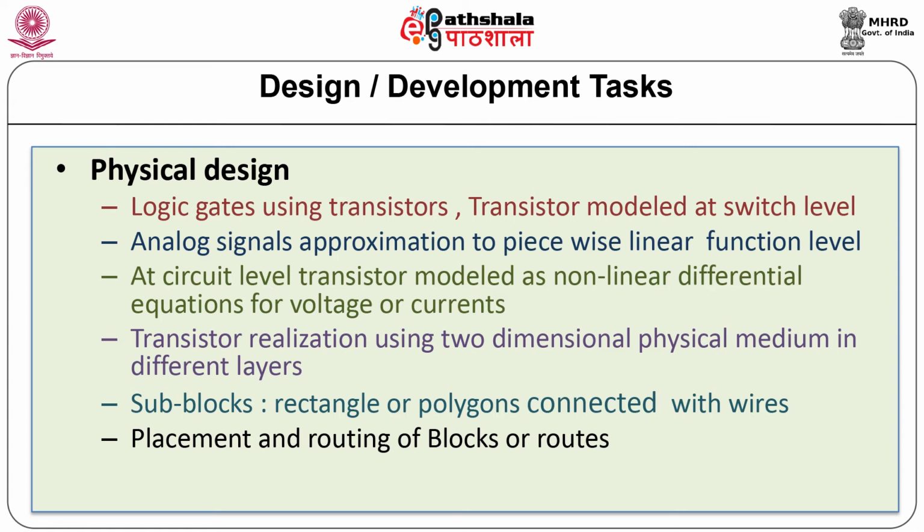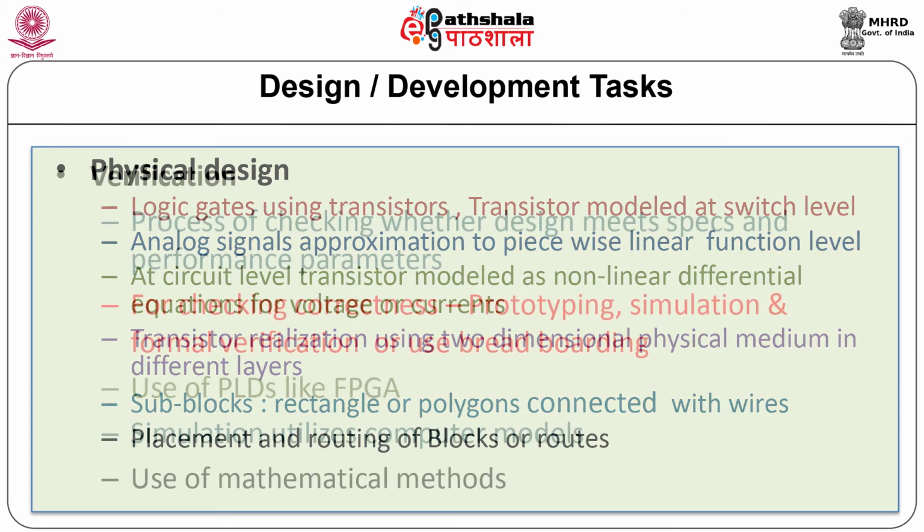These layout designs have some timing constraints. The grouping of subblocks in a structural description and the interconnections need to be addressed separately while handling the partitioning of the layout. Simultaneous development of structure and layout is known as floor planning.